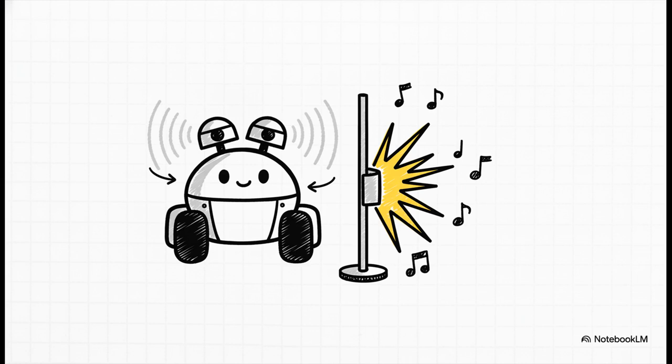This way, if the ultrasonic sensor fails to see something really thin, like a chair leg, and the robot physically bumps into it, the touch sensor acts as a fallback. It must immediately override everything, stop the robot completely, and blast an error sound so you know a collision happened. You'll be continuously monitoring two different inputs at once. It's a real game changer.